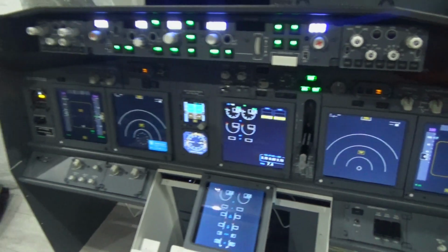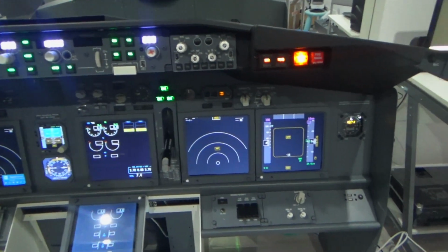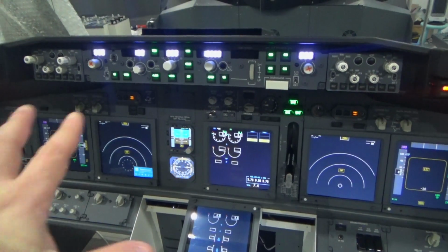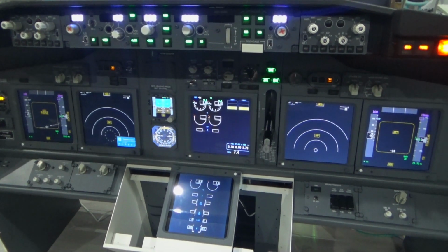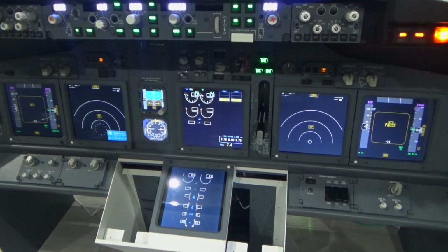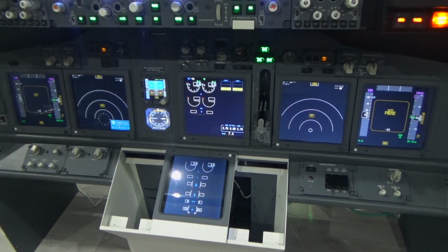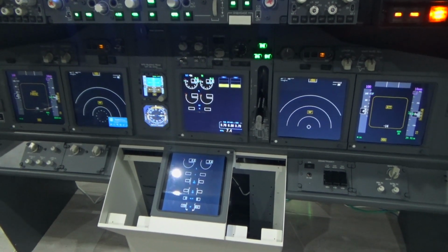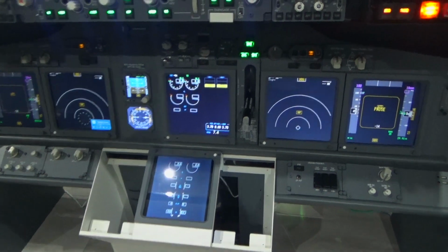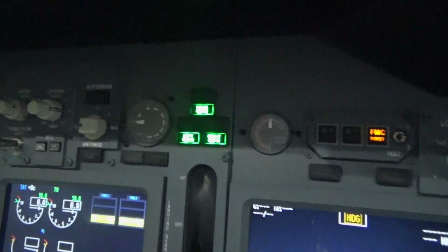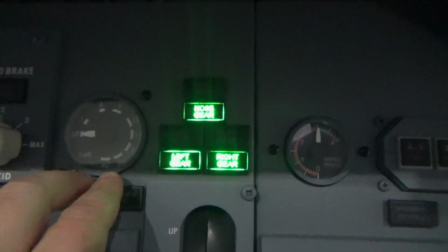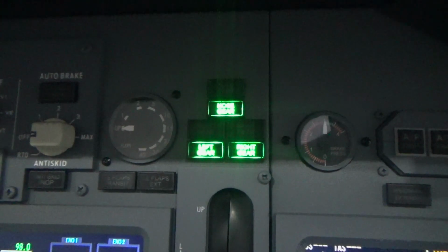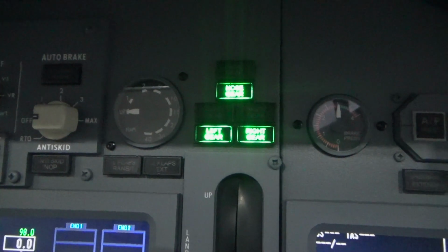So at the moment everything is okay. You configure everything. Now the only thing left to do is to start your simulator, and you can play with it and start testing even further. One thing that I also want to show you, but you can do that by reading the manual: there are two gauges for this simulator, the flaps gauge and the brake pressure. These originally are not configured. You have to actually select the servo motor, and then go into ProSim and configure. It's very easy to do.